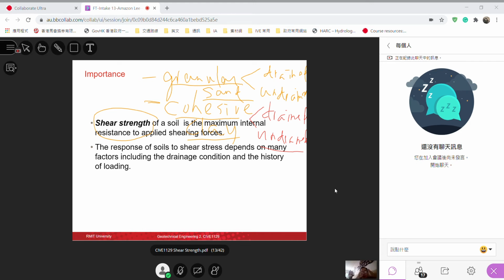So it will stay in there, and because of that, the pore pressure will become an important factor affecting the development of the shear strength. Then you can immediately imagine the complexity of just defining the strength of the soil.